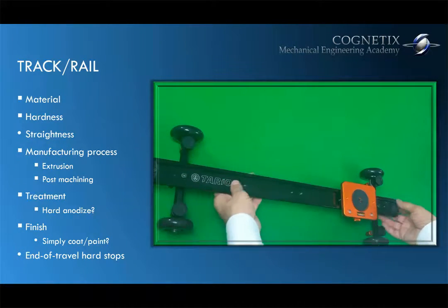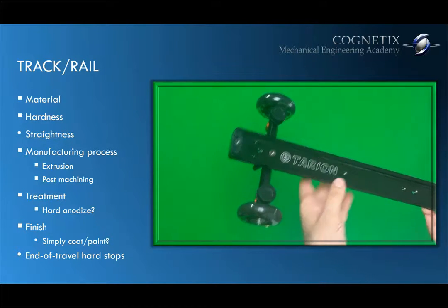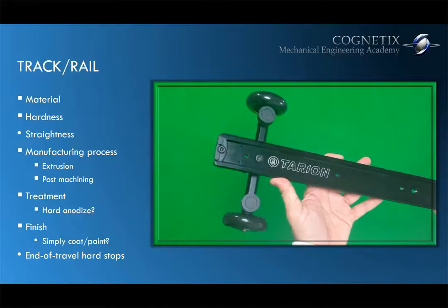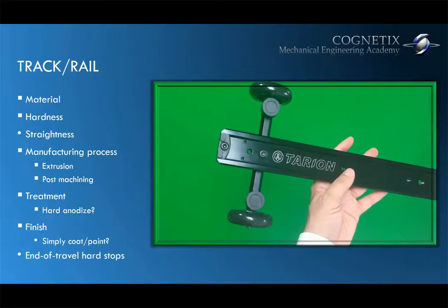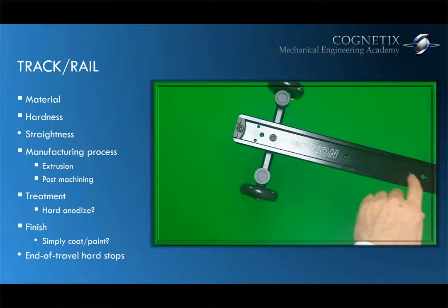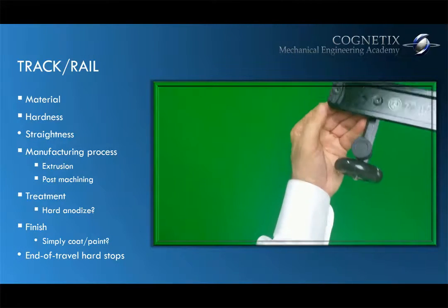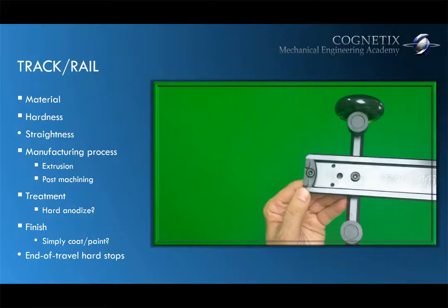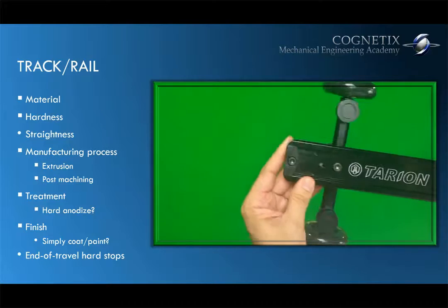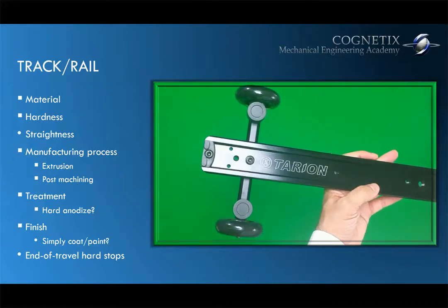So the end result is that the entire length of the material will have a constant cross-section profile. Okay. Now, of course, that's not enough. If they had done that and stopped there, the product would not work yet. Okay. There is some post-machining that takes place. You have an extrusion that does not have any holes. It does not have these curved ends right here. Okay. If we just cut an extrusion, it'll be sharp at the end.